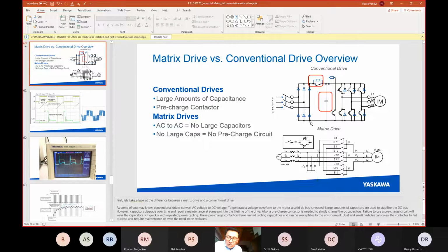These diodes are not controlled. You forward bias them by putting a higher voltage behind them than they have in front of them, and they will conduct. And thus the current waveform here isn't affected at all by our control board, and it's not very good. As you know, current harmonics on a VFD without any filtration here can be as high as 80%, and they're required to be less than 5%.